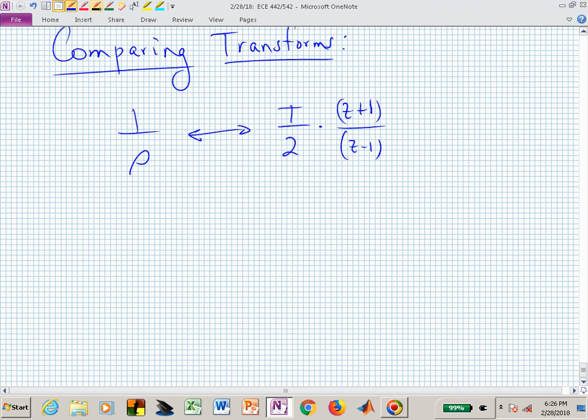And we probably don't want to be substituting that in everywhere we have an s to the minus 1 or a 1 over s. We probably want to just play with s. And this is now 2 over T times z minus 1. That looks familiar. That was always appearing in all of our relationships. Now we just have a little different denominator. In one we had a z, and in the other one we just had a 1, so it's sort of looking like a combination of the previous two.